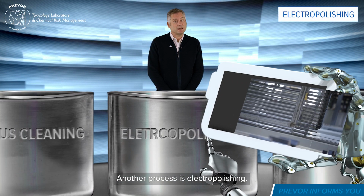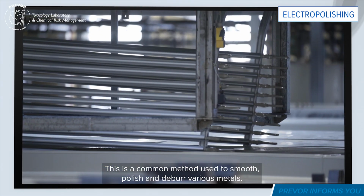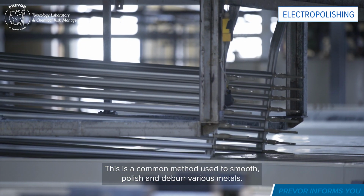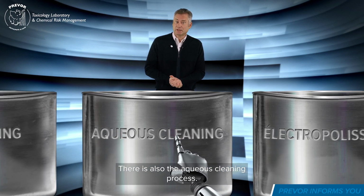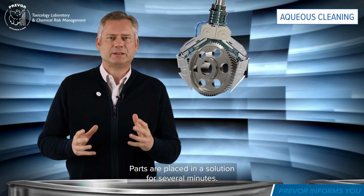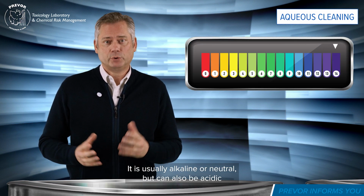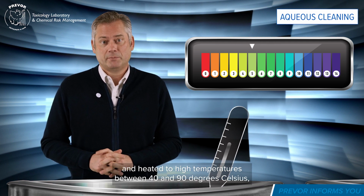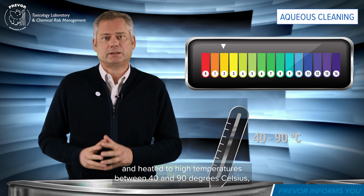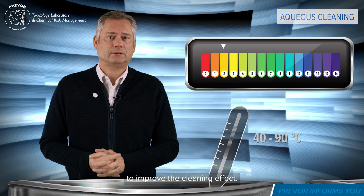Another process is electropolishing. This is a common method used to smooth, polish and deburr various metals. There is also the aqueous cleaning process. Parts are placed in a solution for several minutes. It is usually alkaline or neutral, but can also be acidic and heated to high temperatures, between 40 and 90 degrees Celsius, to improve the cleaning effect.